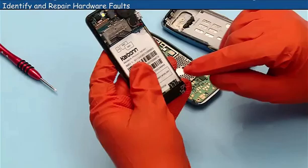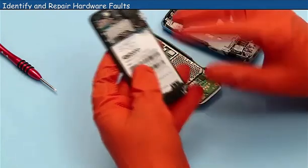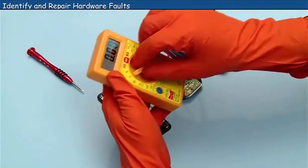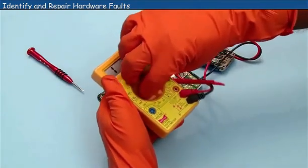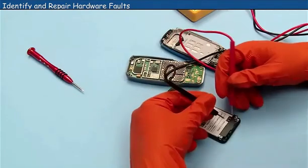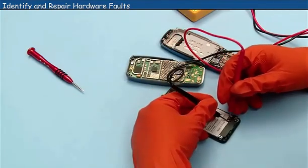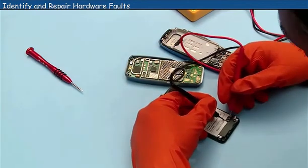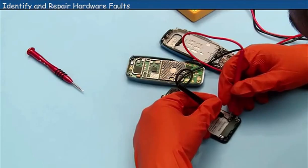To check the battery pin connector in pin type, check the soldering point first. Then, take a multimeter and set it in ohms range. Place the probes between the battery pin and the soldering pad. If a beep sound is heard, then the battery pin is in good condition. Otherwise, replace the damaged part with a new one.